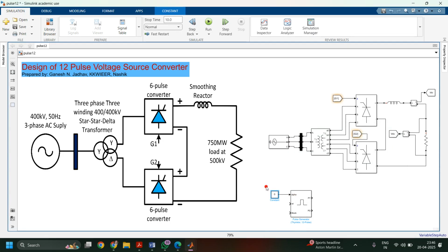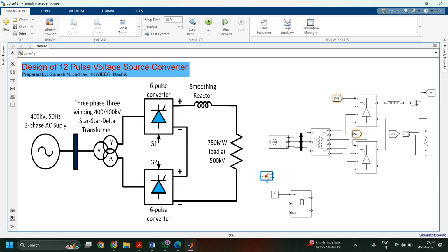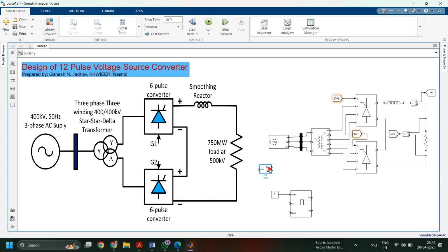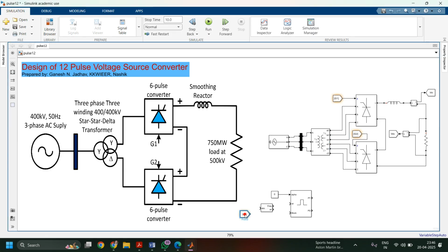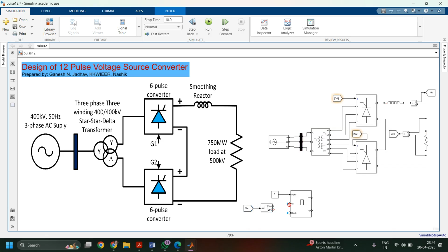Now we have to give the omega t. For taking the omega t, we need a PLL block. So take the PLL. Sorry, we need a three-phase PLL. In this three-phase PLL, the input is from VABC, that is the source voltage, AC voltage. So rename this with VAC and click on apply. So this block's input is taken from the voltage measurement block. Connect this omega t here. The block terminal we will not consider now for the simulation.